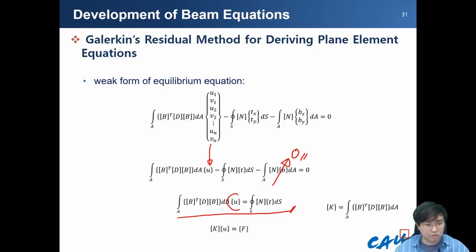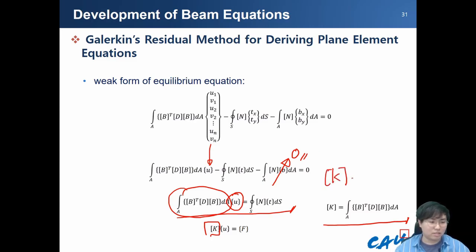Here this part is the displacement u, and this part is the local stiffness matrix, so we can say this equation is the general stiffness matrix of the 2D case, or in the 3D case, you can easily, maybe B with integration over the total volume. Sorry, maybe I made some mistake, we need some thickness.